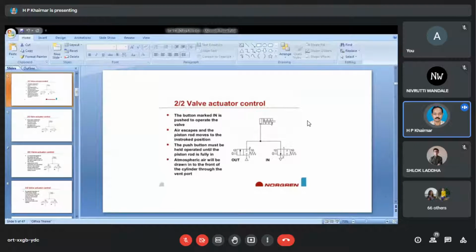So this is what the scenario is. Okay, I can just suggest one thing. See, in the current position, you are applying full pressure with the push button, then it is giving you the out-stroke, and then again from the other end, if you are pushing, then it is getting the in-stroke. But in between this, we can add different elements or valves which we have studied earlier. You can have a check valve, you can have a control valve, you can have a pressure relief valve. These valves will only further improve the functioning of the system, and basically you can regulate the pressure correctly.